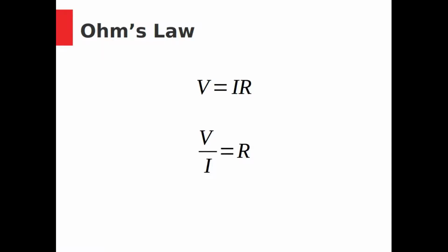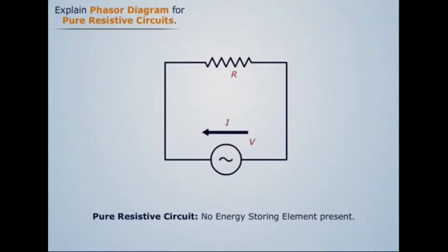Another way to think of this is, if you have a certain voltage, the resistance provides the proportion that tells you what the current will be. The resistance controls the current. So, for instance, if you know that the battery voltage is 5 volts and the current is 0.5 amps, that means the resistance must be 5 volts over 0.5 amps equals 10 ohms. That's the proportion. Now, let's apply this logic to an AC circuit.